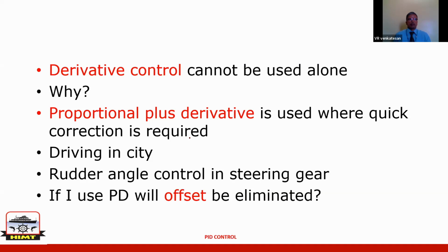Yes, sir. When the required rudder angle is reached, the pump can go to zero stroke. Yes, sir. An output is to be generated in zero error condition for rudder control. So if we work with only proportional, rudder angle control still works. But to make the response quicker, we can put Derivative as well.